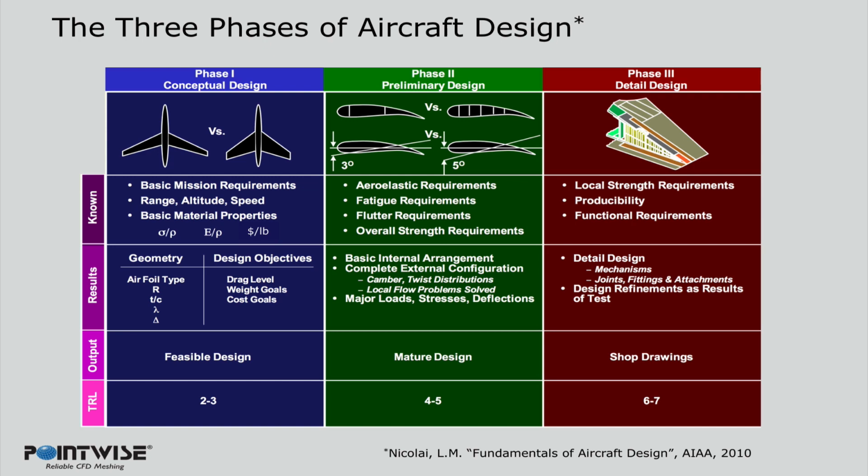Conventional aircraft design is separated into three distinct phases: conceptual design, preliminary design, and detailed design. Each phase is distinct in the varying level of detail explored in each respective phase. A lot of the activities that highlight conceptual design, the earliest of the three design phases, involve a lot of changes to the geometry definition in order to explore a broad design space. Designers will typically need to interact with their design model many times manually, as well as perhaps employ the use of optimization in order to quickly develop designs for comparison.